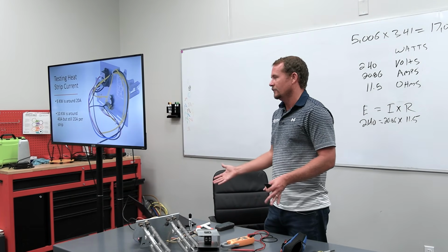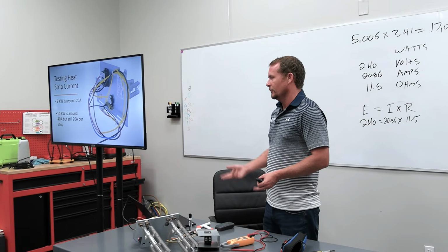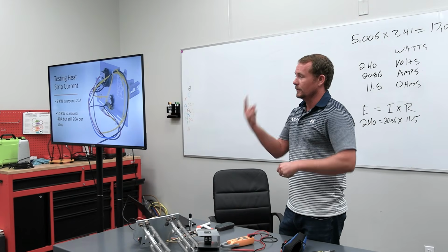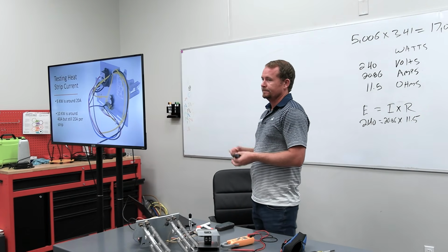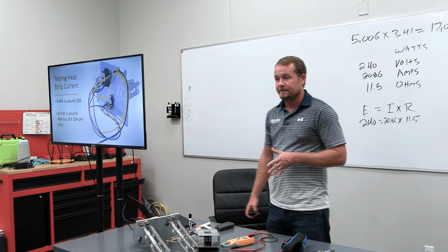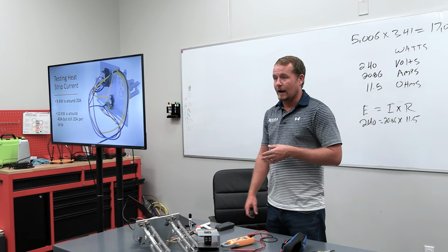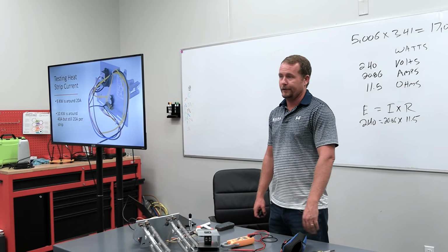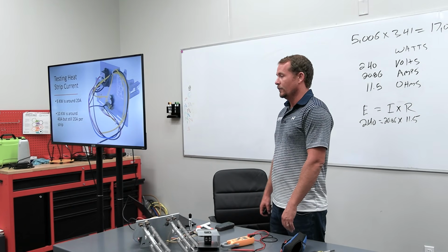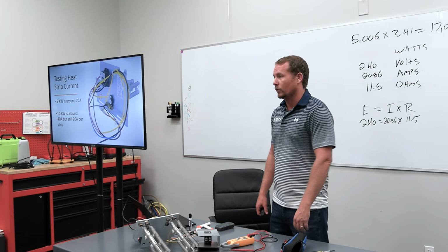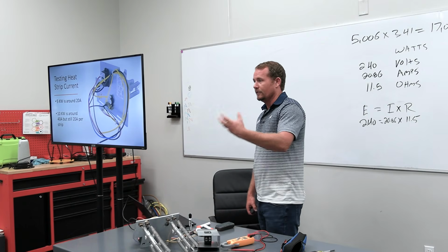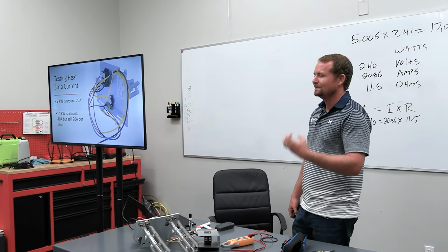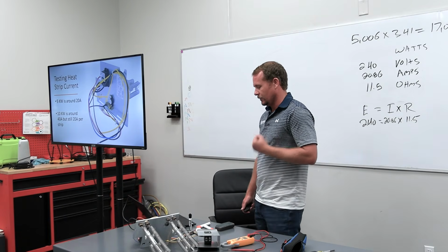The point being that you're going to see 208 when the building is a 3-phase building and you're only using 2 legs, and that's what this is. This is single phase equipment hooked up to 2 legs of 3 phase. So when that happens, you're going to see lower output, which means you're going to see lower current. So just because you were to measure 18 amps on this, you might think, oh, well, this heat strip's not working properly. No, it's just that the input voltage is lower. So input voltage lower equals lower output, lower current.